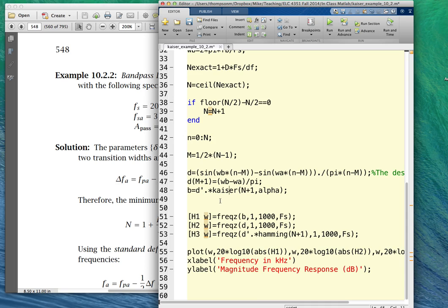The last thing I want you to do is plot the frequency response for both the Kaiser methodology, a rectangular window, and a Hamming window. This is code that lets you do that. It turns out freq_z lets you specify an output. When you give it an output, you can get the frequency response, which would just be a series of complex numbers at each frequency value.